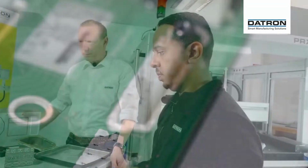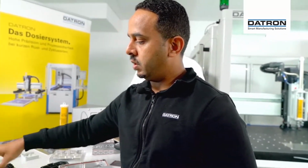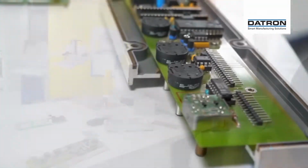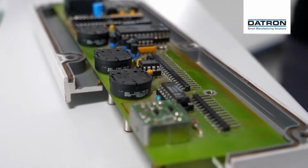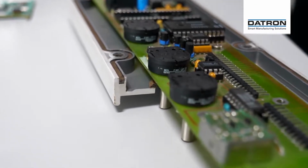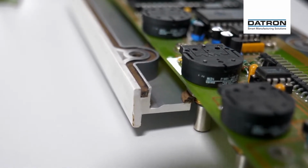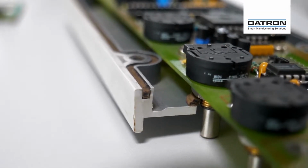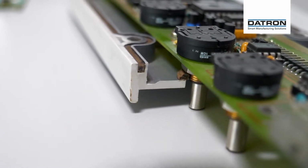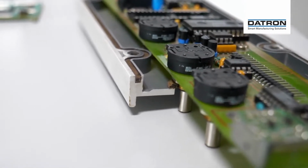Okay, I guess that's all. Did we talk about the Combi dispensing? Yes, here we have a Combi dispensing. This is a DATRON specialty where we have the EMI material and silicon together. The core of the EMI gasket is silicon, and the EMI material is outside, as the cover. And this cover is the functional part, the EMI shielding part, and what is happening inside doesn't matter.